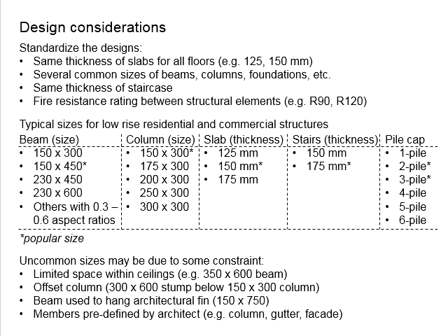Let's say now you decided the slab to be 125, or if you have a larger slab, probably 150, or if you have a much larger slab, probably 175. The bottom line here is you make sure every floor the size of the slab is more or less the same. That one is for the economical aspects, and you make sure all the floors have a similar thickness in terms of the slab. This one is for the consistency as well as for the practical aspects.